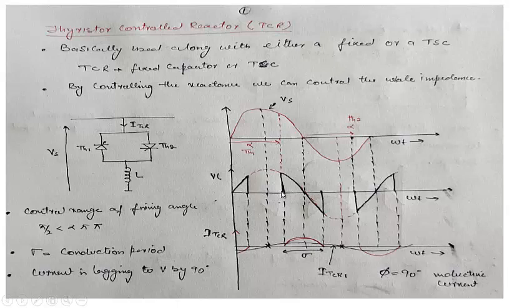The total voltage area from here to here will be equal, so that net voltage or average voltage between them will be equal to 0. So this is the current pulse, we can say, for this thyristor, and then TH2 will be triggered at alpha greater than 90 degrees. Alpha will be measured with respect to this point, and this will be its alpha, which will be greater than 90 degrees, and it will be equal to this alpha with respect to 0.